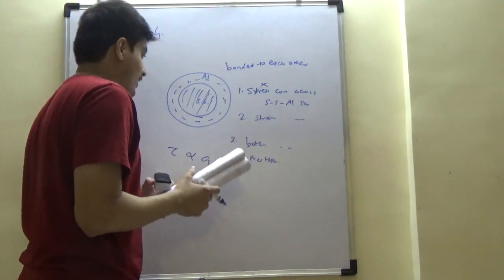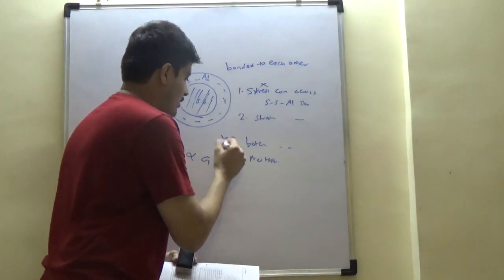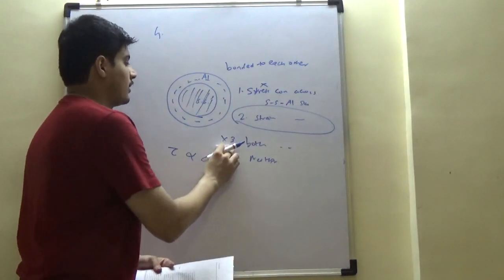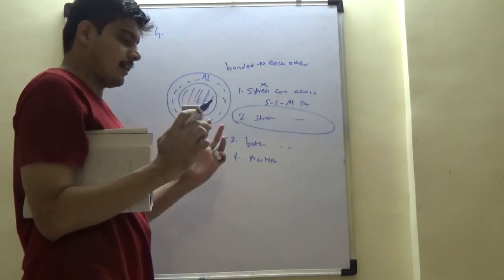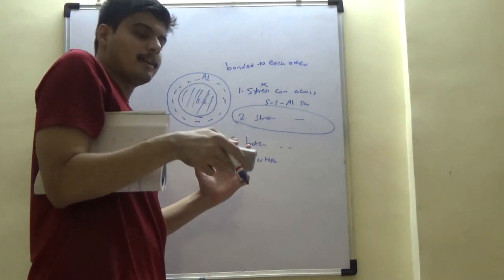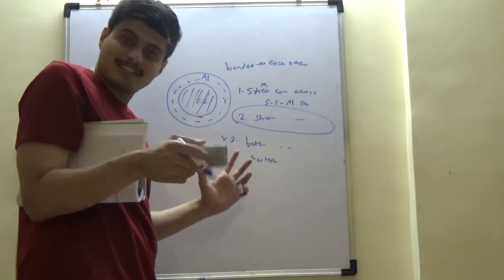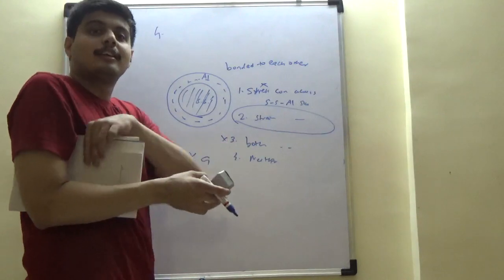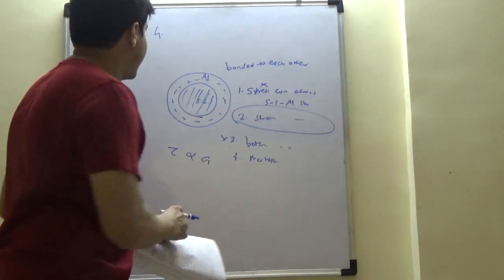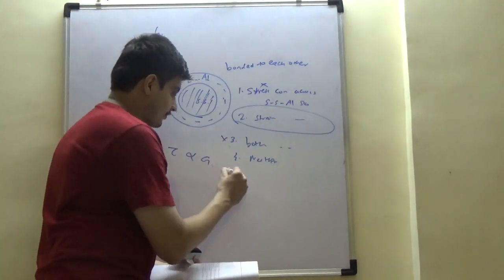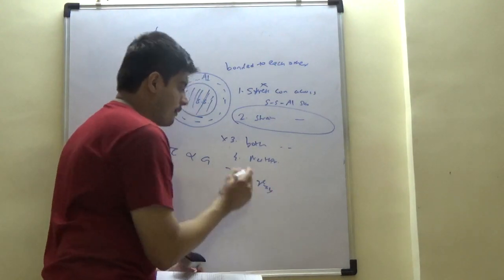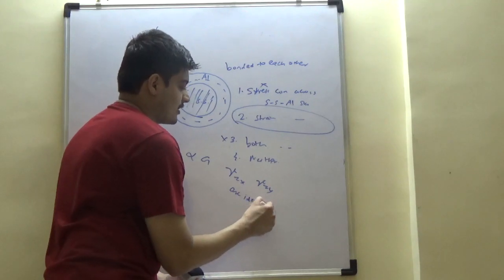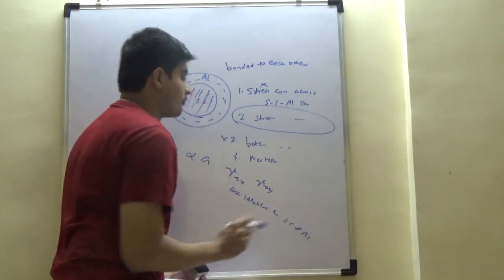So stress can never be continuous. So these options are gone. This option, or the fourth, is a problem. But as we said, since it is bonded, none of them can have independent twist. And if the twist is the same, the theta dash, the warping is 0, because we have seen the displacement fields u and v will dictate that your gamma zx and gamma zy are identical in SS and aluminium.